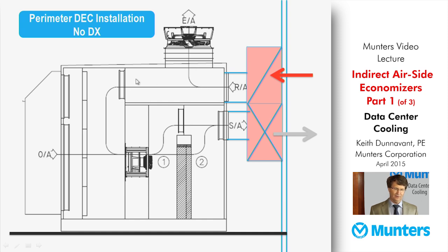Some during the winter months is recirculated, and we often have a 1/3, 2/3 damper segment, so that during the cooler periods we operate the upper segment of dampers to promote better mixing with this warm air before it then enters the supply fan and can go through segmented evaporative media stages. 4-inch and 8-inch media in series is common, with a modulating bypass damper.